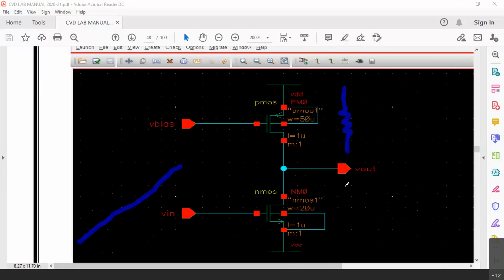Let us say this is like a switch, and if this switch is closed, NMOS is closed, then this particular point gets connected to minus 2.5. We are taking output here, right? Now my point was output remains here at minus 1.2. It does not go here.